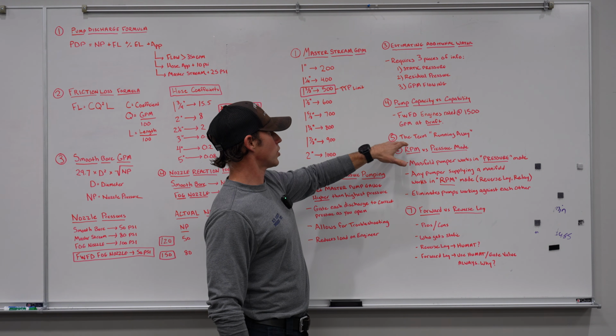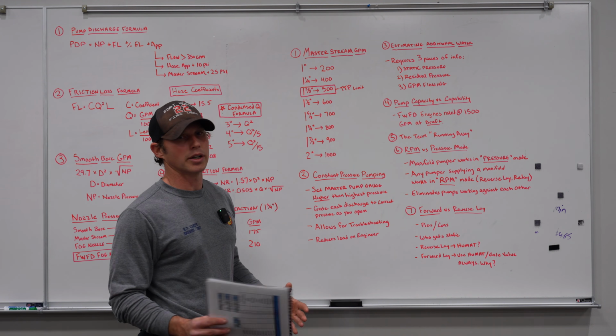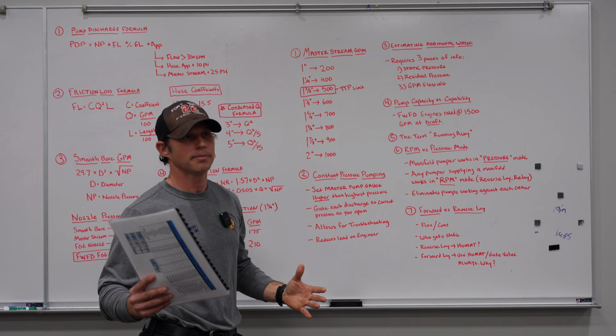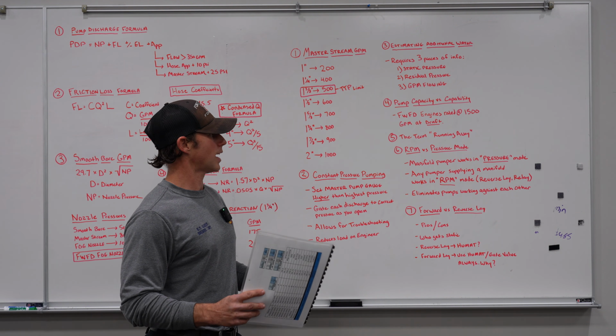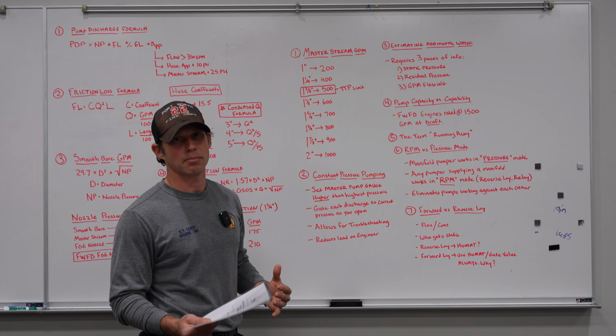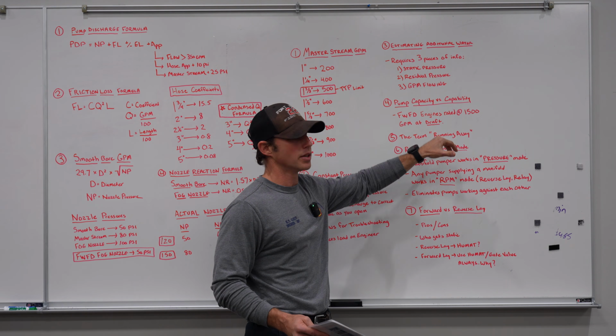We'll address the term "running away," which is kind of slang for your pump running away from the water. Essentially, it means you're trying to pump more water than you have, more than your supply. This could lead to cavitation, so we definitely want to avoid that.